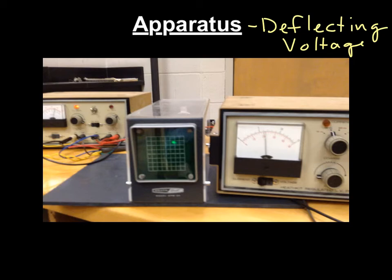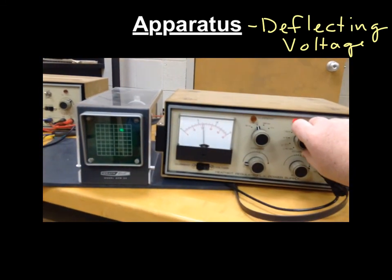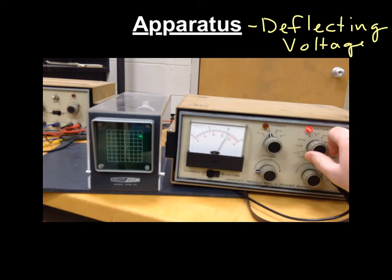This is the right side. This is the deflecting voltage. So let's look at this. You will turn this knob right here, and it will increase the voltage. And as you can see, the dot that started right here moved over this way as this went up. Eventually this will max out.